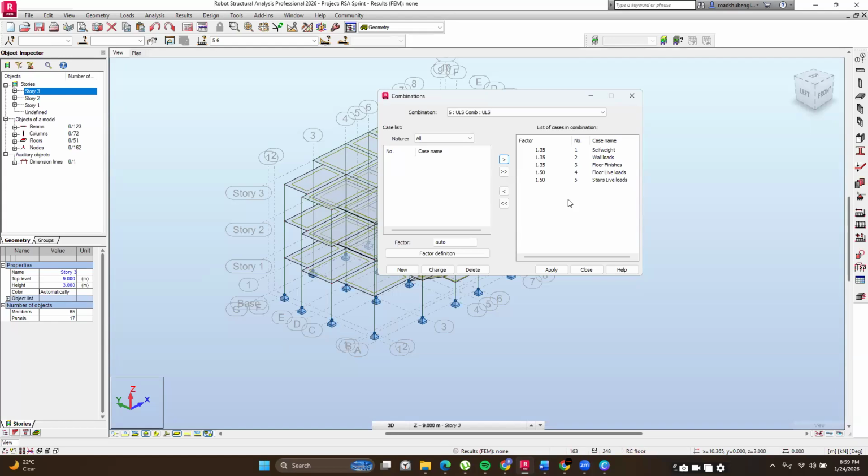Probably the masonry blocks that are going to be used to construct your wall are going to be heavier than you intended them to be. So for that particular case, you have to multiply them with a factor of safety so that you can account for those deviations.